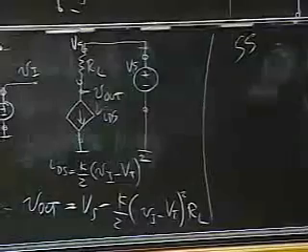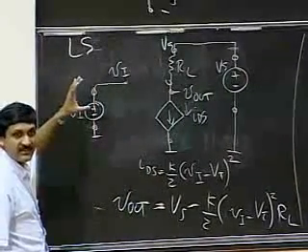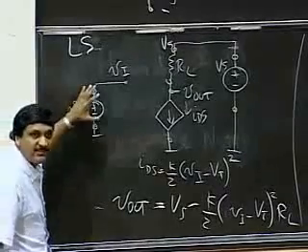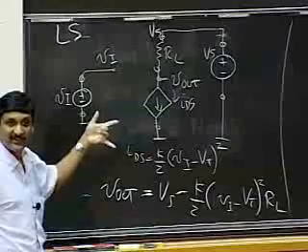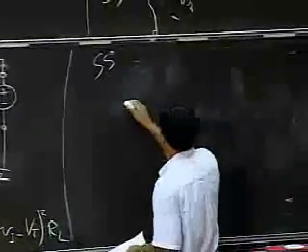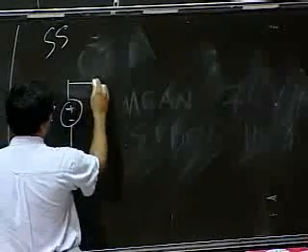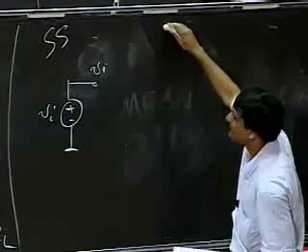And the method says simply pluck out each of these elements, and simply replace each of these nasty nonlinear elements with the corresponding small signal linear equivalents. So let's do that. For the input, you replace the input with its small signal voltage, because I'm telling you that it's sourcing a small change in VI. So that's vi.